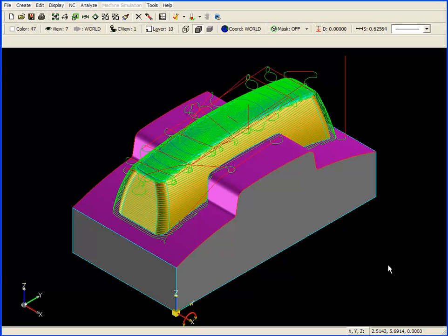When we look at the created tool path, you can see that we have avoided the purple surface completely because it was set up as a check surface, but have cut the rest of the part. So in conclusion, a steep shallow cut is a good cut to use if you have a part that is a combination of both shallow and steep surfaces.